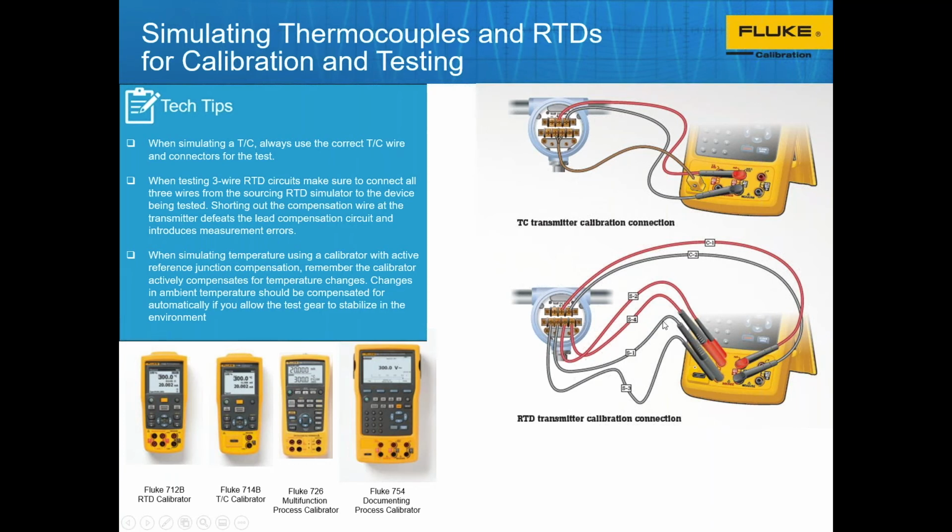Use a full length of test lead of the same material. So don't mix and match your test leads, I guess is the takeaway, and use something simple like our stacking test lead jacks. And that gives you a single point into the device, but it allows you to terminate both very close to where the measurement is being made.